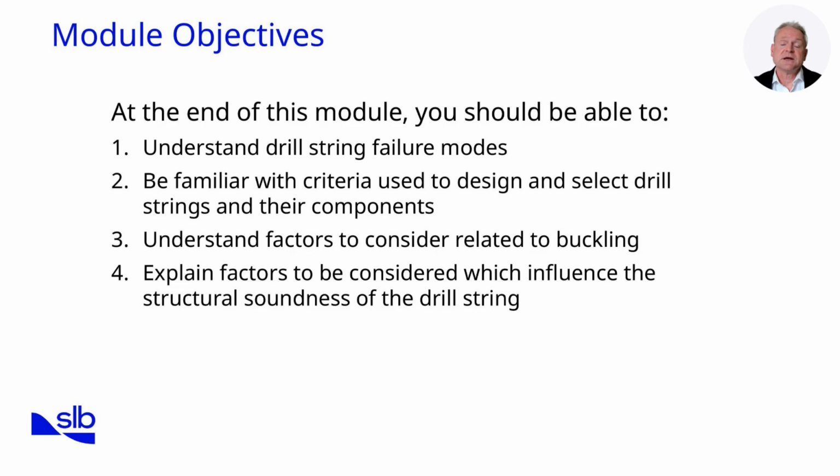Drill strings are subjected to intense mechanical loads, including torsion, tension, and bending, as well as fatigue cycles caused by continuous rotation and changes in well trajectory. To design an effective drill string, engineers must balance structural strength, flexibility, and operational performance. We begin by addressing fatigue, one of the primary causes of drill string failure.